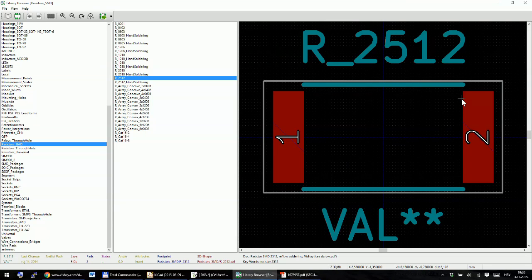Well, I think I will go with this footprint when I think about it, because this will be used in a marine environment, and I want to have exposed tin or copper, exposed soldering, as little as I can. And these components are so big, it'll be much easier to solder.